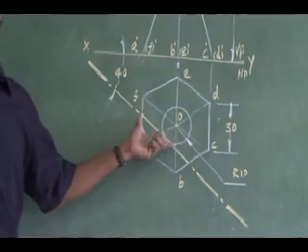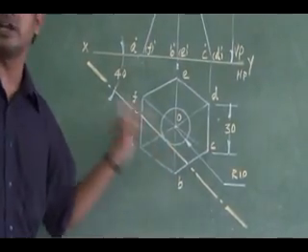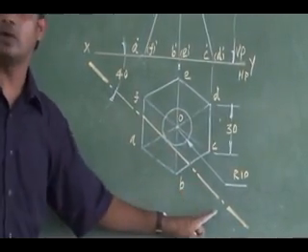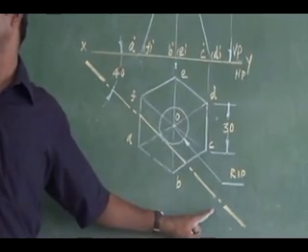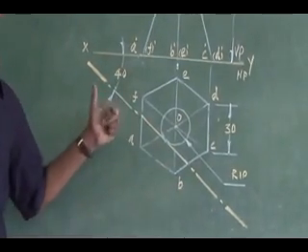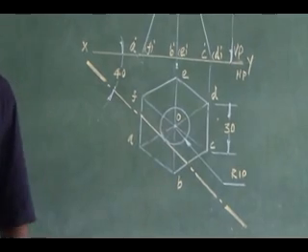Whatever portion it cuts the solid, inside that solid it should be continuous. Outside you have to represent the cutting plane representation, right? That is the axis line, at both the ends it will be thickened.